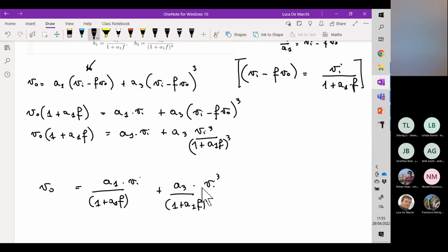Minus 20 dB per decade, which means a reduction of a factor of 10 every increment of 10 in the frequency domain. So in the bilogarithmic plot, the hyperbolic relationship between gain and frequency turns into a linear relationship.